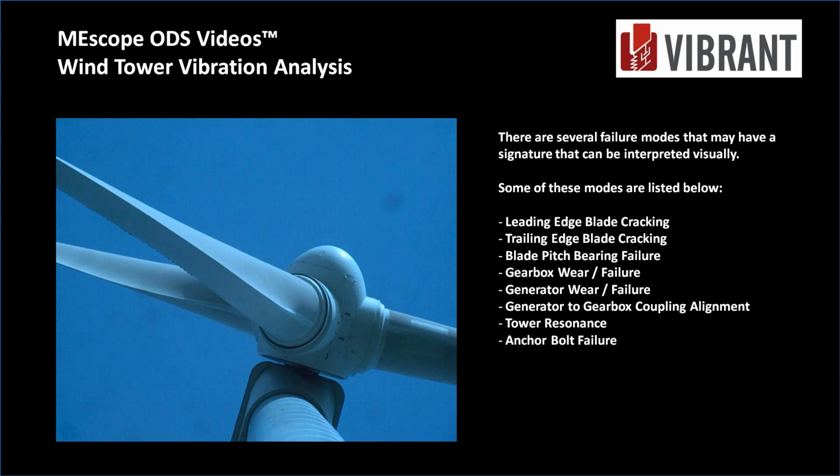And the last failure mode is anchor bolt failure. There's, I don't know, maybe 50 anchor bolts in the base of these units, and you shoot the ground and you see motion. It's not much motion, but you're at the attachment point. It's a little hard to interpret how much is too much, but we didn't see any cracks opening up, anything like that, which was good.